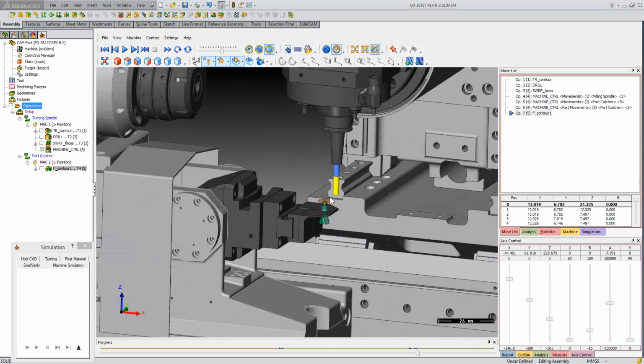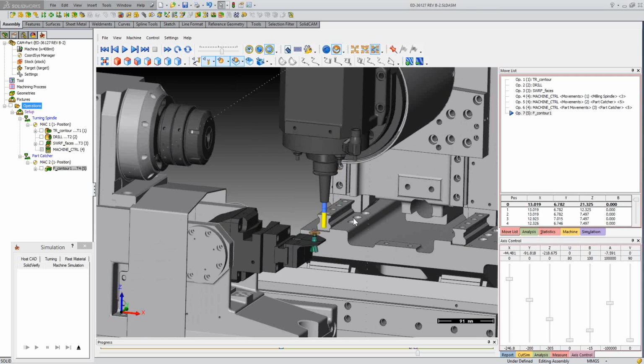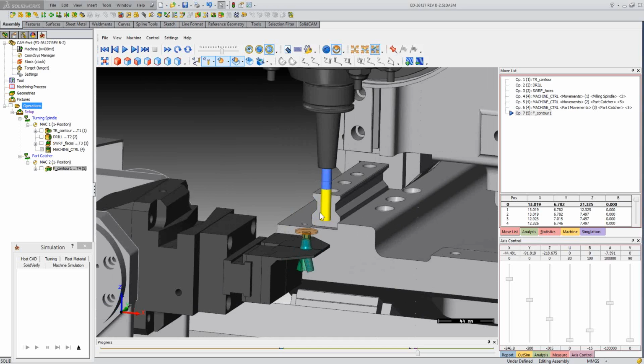Also here on this device I can define positions. On Mach 2, position 1, I can continue to define position 2, position 3 on angles, and use the B-axis on this part. Okay, we are limited by the machine, by the B-axis limits and by the X, Y, and Z axis range, but it's definitely possible to work here on different B angles.